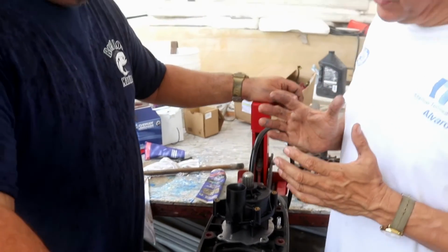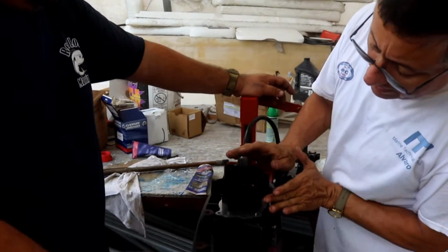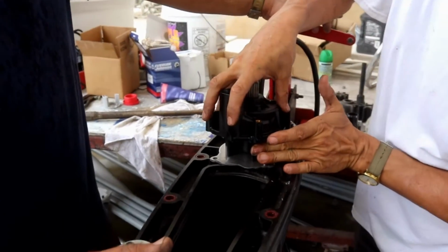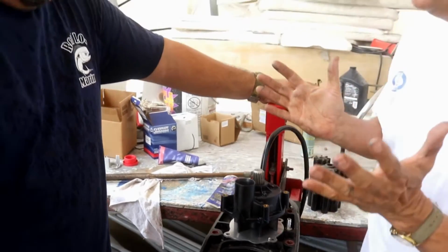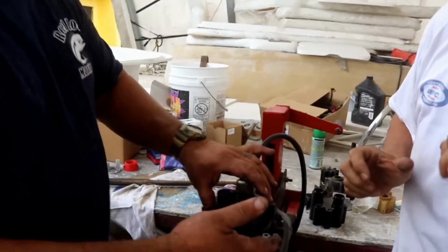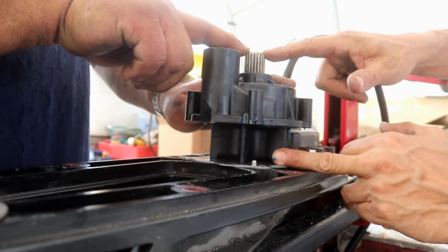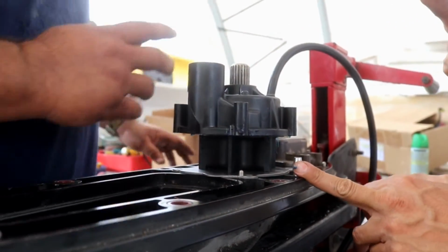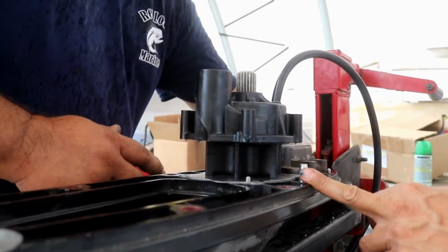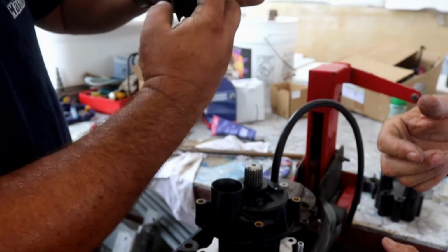Danny, the $1 million question where people make a lot of mistakes is how you introduce the housing into the impeller, protecting the impeller. What is the process? So here's the deal. Obviously, we put the grease in the housing so we don't damage the impeller, and you have to know the rotation of the engine. What is it? It's clockwise. Okay. So if it's running clockwise, it has to spin like this. So this has to go in.